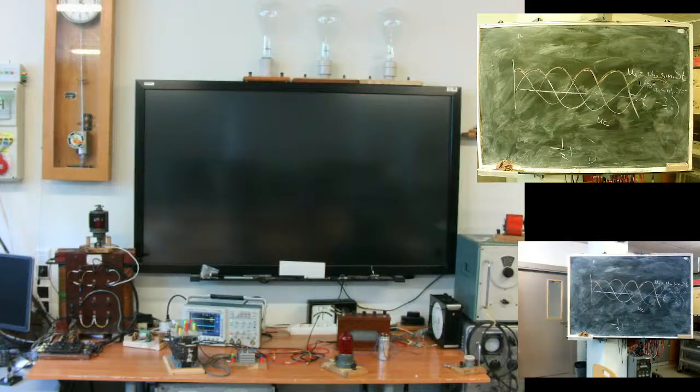This is how to calculate. You will get this difference because the star delta transformer has a complex transformer ratio. It implies 30 degree shift. And the shift is different for 50 and 250 Hz components.